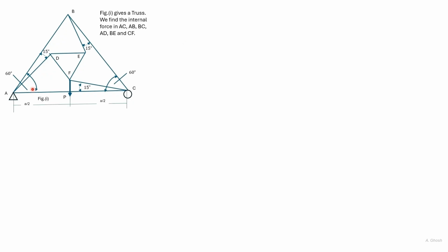Similarly, with this section, resolving forces in the vertical direction will get a relation between the forces in BC and CF. And resolving forces in the horizontal direction will get the force in BC and CF in terms of the force in AC.